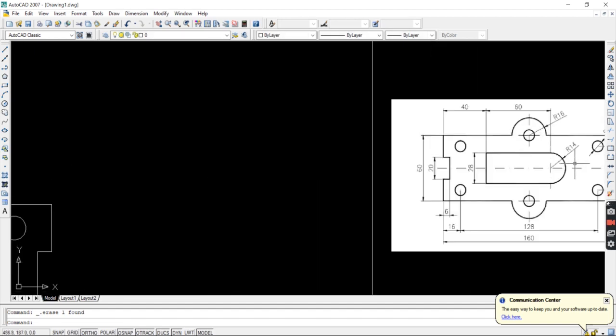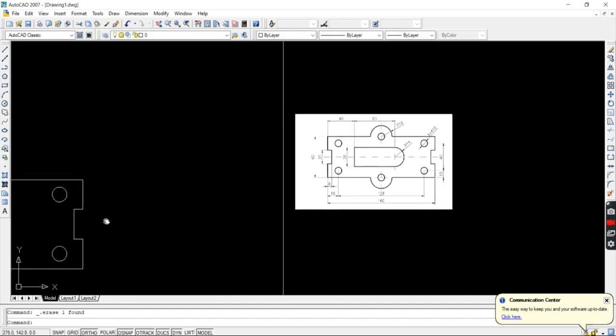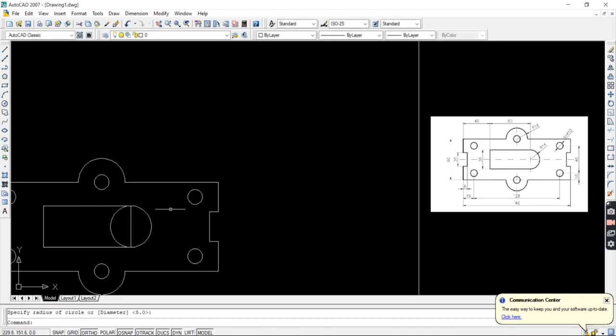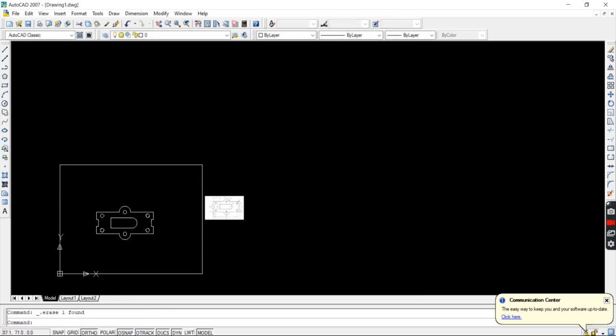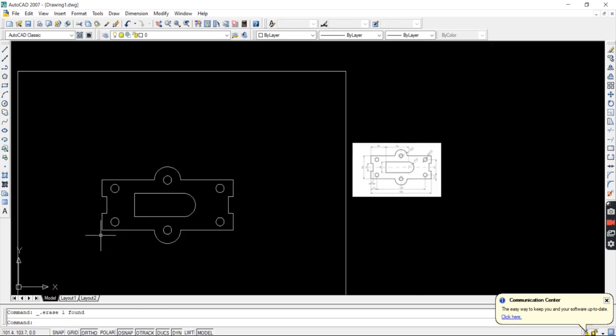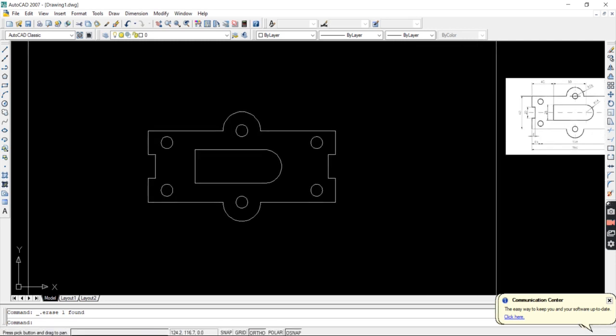All right, just draw this arc. The radius of the arc is 14. I can just select this midpoint as the center of the circle and select this as the end. Now type trim. All right, select these two lines, enter, then click on this. Okay, remove this line as well, and here we have it. The figure is complete. Now you just have to dimension it.